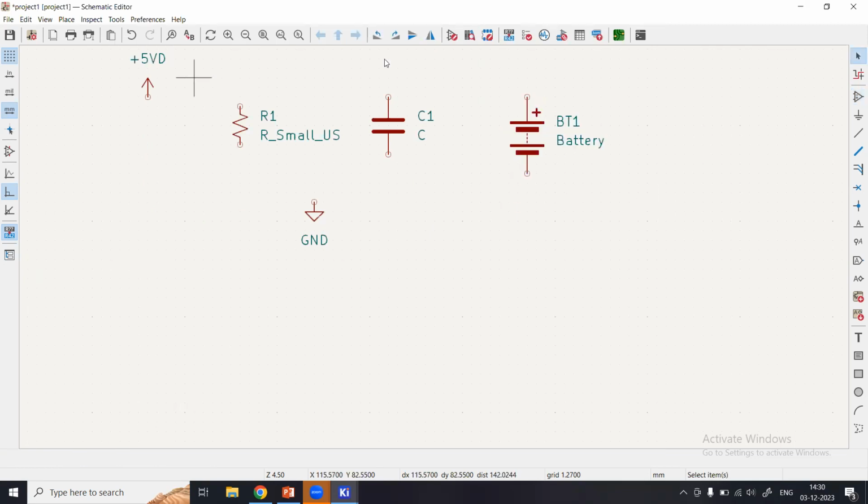And I don't want that. Instead, I want to use some option. For example, where is the wire? Here it is, add a wire, and below is the bus actually. So click here, connect the capacitor. Click here, connect the resistor. Then connect to the ground. Connect to the ground. Again, connect the capacitor. Then you go and connect to this one. What to do with this symbol here for the voltage source?